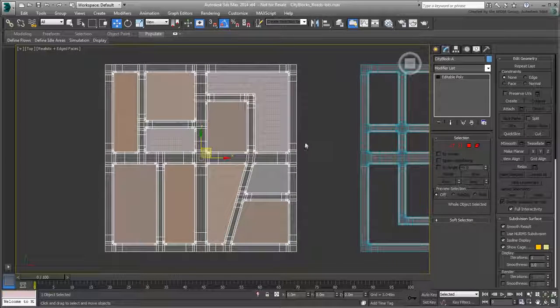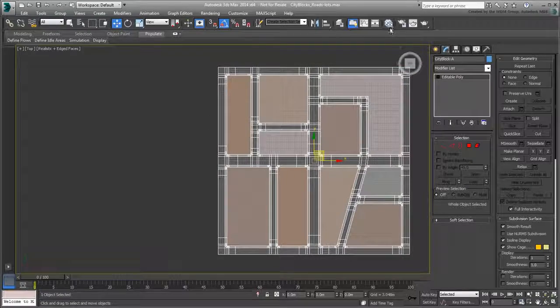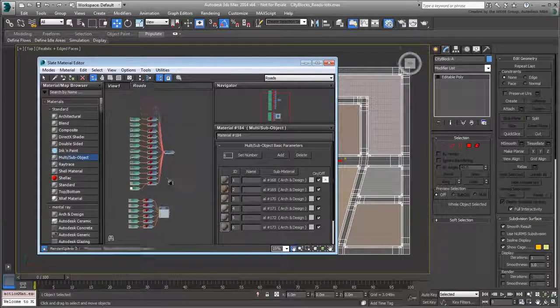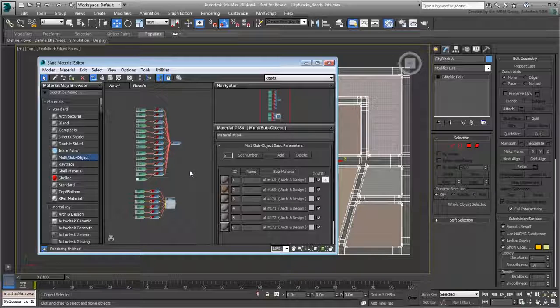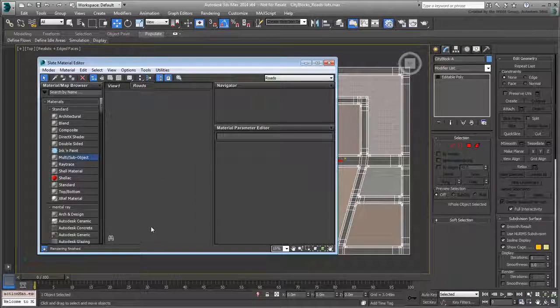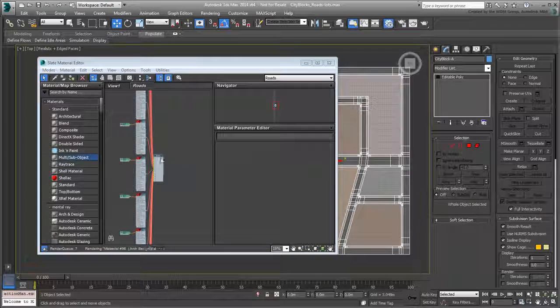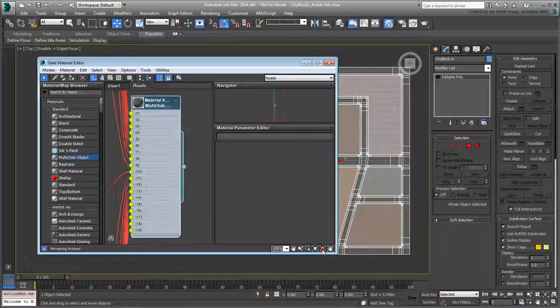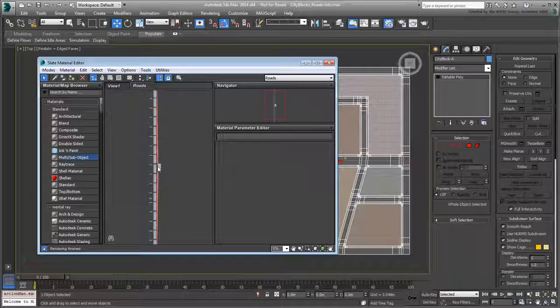Finally, you need to consolidate your material as you have learned to do. In the Material Editor, select all nodes as they apply to the roads, sidewalks, and building lots and delete them. Use the Material Picker and click the city block in the scene. You now have one large multi-sub-object material that affects all parts of the city block. Rearrange the material nodes as you have learned to do.